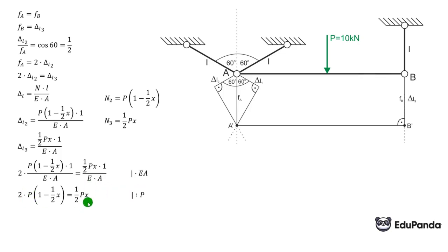Well, I won't go overboard with these simplifications here. We calculate that x is 4/3 times L, which is 4/3 meters. And that's all, that's what they asked us for. At that distance, x was marked on the left side, meaning the force P should be applied at that distance on the left side for the downward parallel displacement of beam AB to occur.